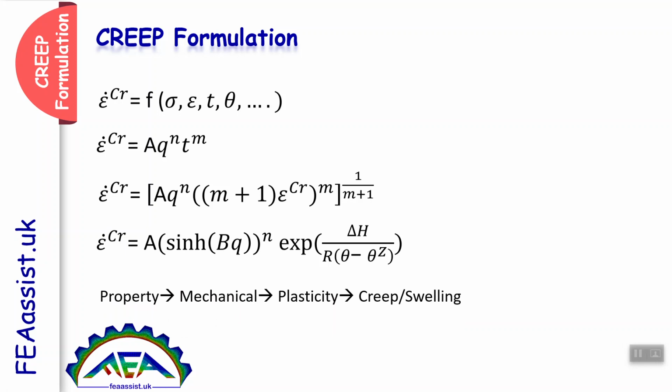So you need a place to write your creep formulation and force Abaqus to solve the creep problem based on your new equation, which is not one of these equations. This place is the creep subroutine.